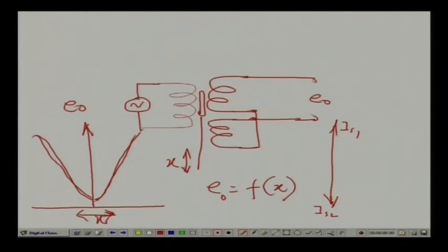Now, you see there is always some null voltage which will appear. This will actually be Ex, the excitation, right. For this movement you will always find an output voltage, and there is a phase difference between the input excitation and the output, which is an undesirable property.